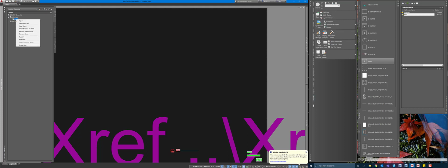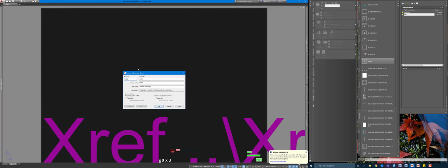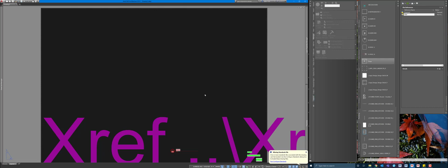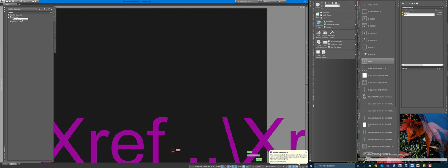It just gets relinked. So what I'm going to do, you right click, rename and renumber. You can also rename the file in Windows through the rename and renumber sheet set manager properties bar here. You just can't have the sheet open when you rename it. Say OK. There we go. So we have our first sheet in the sheet set manager.